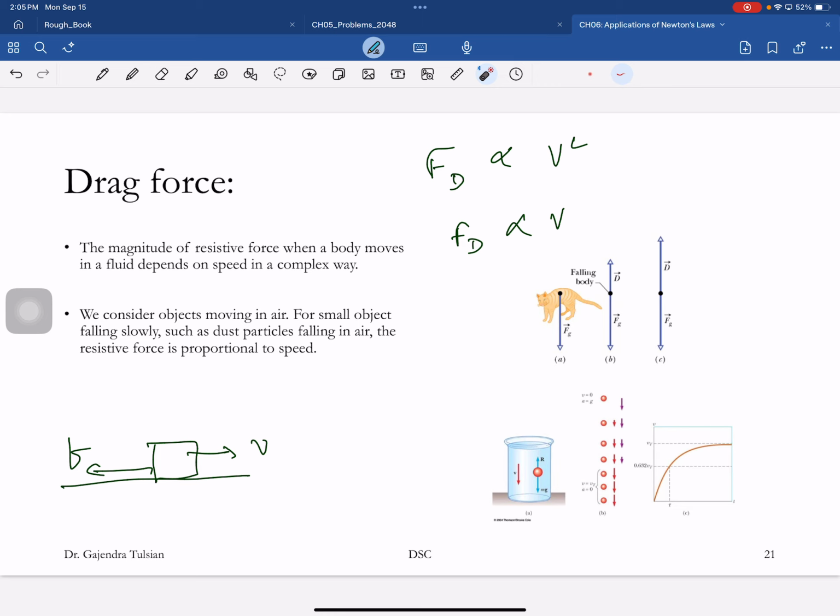When you're driving your car, do you know where you're spending most of your gas? Pushing air out of the way. Half your gas is for that. So you try to minimize this drag force by making the car aerodynamic. What you're trying to do is reduce this coefficient. For your car, this number C is better than for the UPS truck.